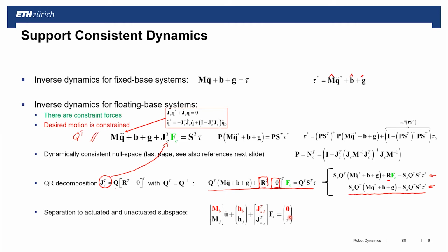So in other words, all we were doing here with these projectors is reducing from a problem which is depending on Q double dot or U dot, force and torque, to only have two of them in there, such that they can directly relate the desired motion to the torque or the desired motion to the force. But it's only a rearrangement, so I'm solving the problem in one subspace first and then going to the second subspace. So I hope this clarifies it a little more.